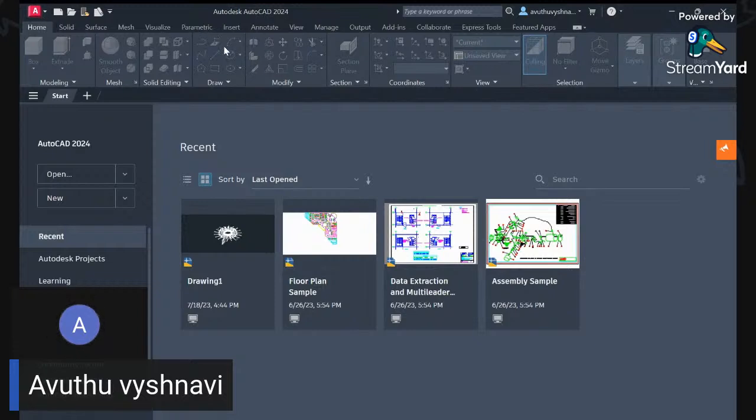So follow my cursor to understand what I'm saying. The red solid button, capital letter A, is known as the application button. In this we'll generally have, as we all know, a new drawing, old drawings, and DWG Convert, which is used to convert your drawing into PDF or docs or something. DWG Compare, where you can compare both the previous drawings and the normal one, and Recover, where you can recover the old ones and start drawing.